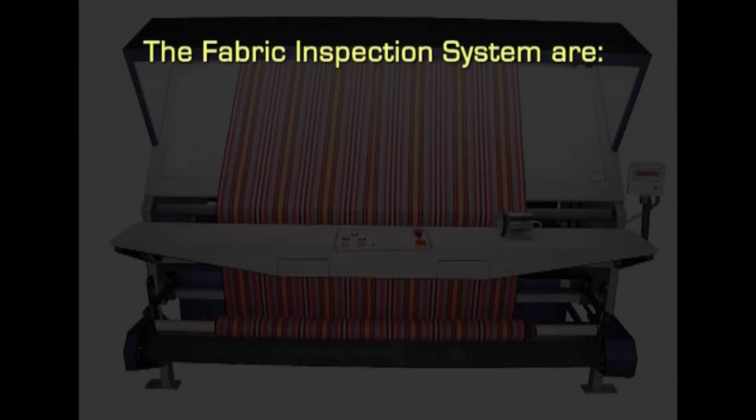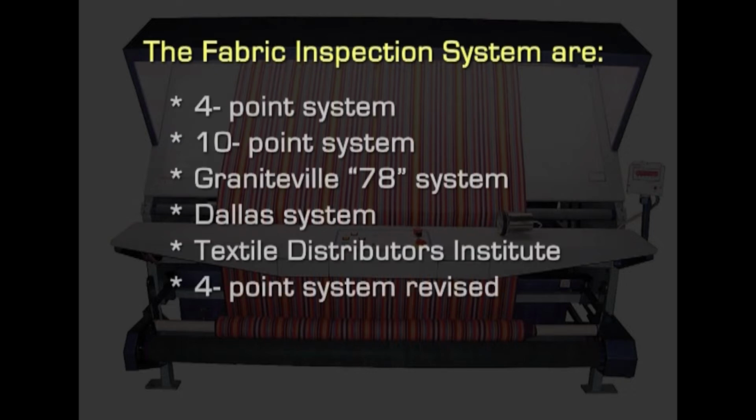In fabric inspection, several aspects of fabric are checked. Fabric defects such as a hole in the fabric, barrier effects, different types of stains, off shade or shade variation, etc. In fabric inspection, sometimes fabric strength, color, handle, quantity, etc. are also checked. To check fabric defects, different systems are in vogue. They are the 4-point system, 10-point system, Graniteville 78 system, Dallas system, Textile Distributors Institute system, and 4-point system revised.